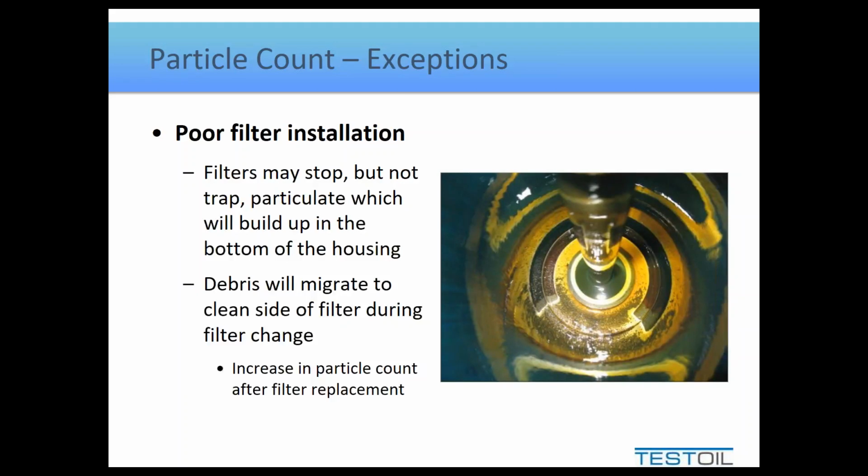The other issue, and this is the extreme case, which is in the picture here, is that you may have so much particulate that jumped across from dirty side to clean side that you're now affecting the filter's ability to seal on that bottom seal. And therefore, even though you install a filter and it feels firmly in place and you tightened it and it feels tight, in fact, you've got bypass along the bottom of the filter because you've got all that debris that will basically erode away as oil begins to flow, and you get a path of least resistance down at the bottom of the filter outside of the media, and you'll have full bypass within the filter. You won't know it. You'll only see it later once you start doing your particle counting or look at your differential pressure.